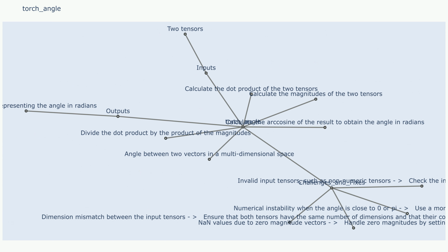Increase welding current, increase the welding current to increase the heat input and penetration. Use a larger diameter welding electrode. A larger diameter electrode will increase the heat input and penetration. Challenge 3: uneven weld bead.